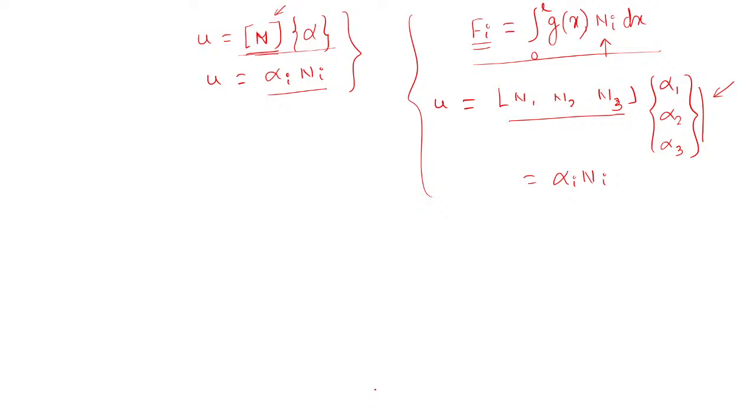Yeah, so coming to your previous doubt, deriving the stiffness entries and other matrices is basically the same as whatever we did in this course. You first derive the weak form, and once you derive the weak form you just substitute the primary variable and the weight function in terms of the basis functions, the linear combination of the basis functions.